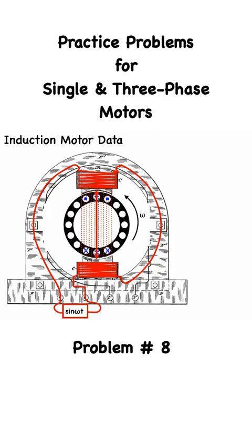This induction motor is a 1 horsepower, 2-pole, 240 volt motor operating at 60 Hz, and the rotor is rotating at a speed which generates a slip of 0.036. After stator winding resistance measurements, no load testing, and locked rotor testing, the equivalent circuit looks like this.